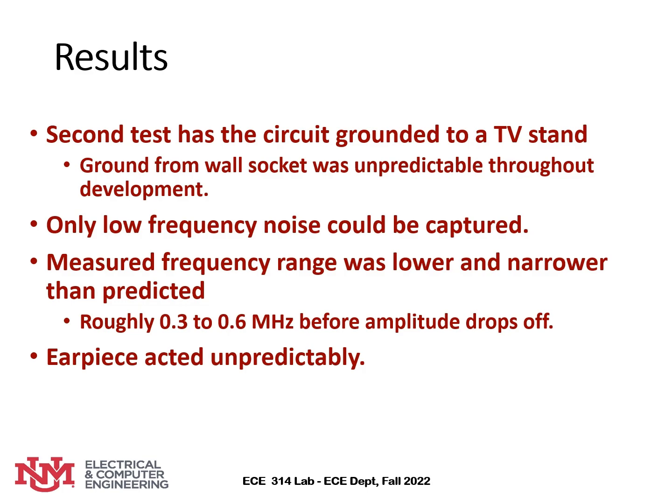Unfortunately, I can only capture low frequency noise, and measured frequencies in that first video. The measured frequency range of the circuit was lower and narrower than predicted. It's roughly in range of 300 to 600 kilohertz before amplitude started really dropping off.